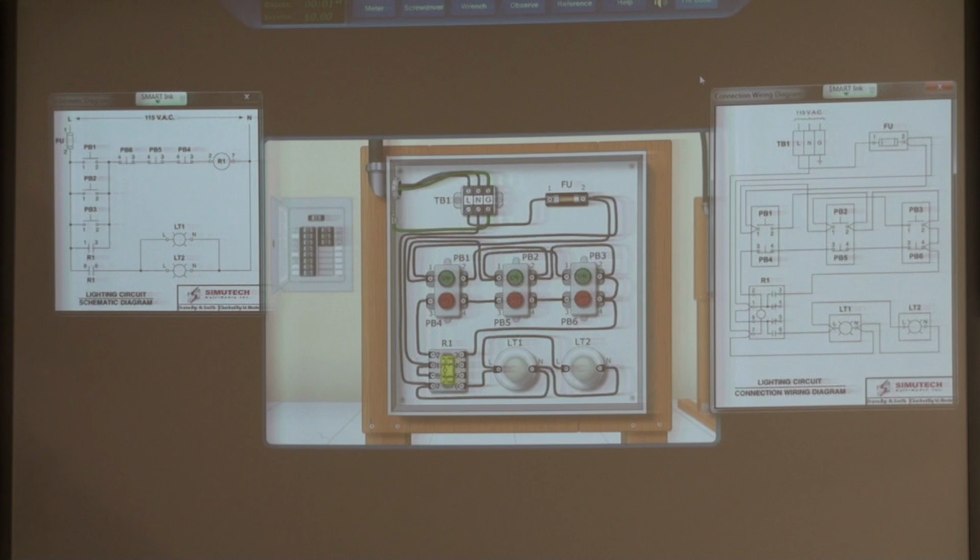The only way you're going to change the normally closed to an open state and change those normally open contacts to a closed state is what? Energizing what? The coil. Okay. So we seem to have that pretty well down, and hopefully by now we know the difference. What type of contact on the relay are we talking about there? Normally open. If it were normally closed, it would have the slash, and the slash connects both sides, so that's a closed state. So an open state is the two parallel lines without the slash. So that's the way we can remember that.